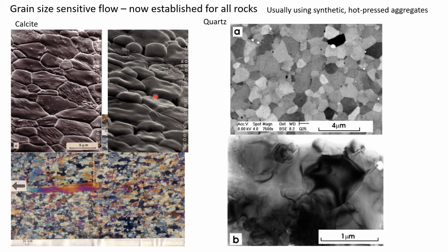The grains have been sliding out of the surface, one with respect to the other, indicating the nature of the deformation. In the slide beneath that, we can see that after quite a large strain, the grains remain equidimensional, and the true strain is indicated by the deformation of this large embedded grain, which has been stretched out by a factor of 10 relative to its original grain size.